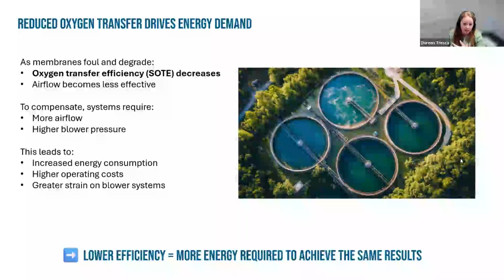Beyond what you should watch for, there's also an impact on the oxygen transfer efficiency, so your basins are not going to operate as effectively. As the membranes begin to degrade and fouling builds up, oxygen transfer efficiency, which you'll often see referred to as SOTE, begins to decline. What this means is that the air being delivered into the basin is less effective at transferring oxygen into the water. To maintain the same DO, or dissolved oxygen, levels, the system is going to have to compensate by increasing airflow. That's what we mean by saying you're going to have to turn up your blowers.